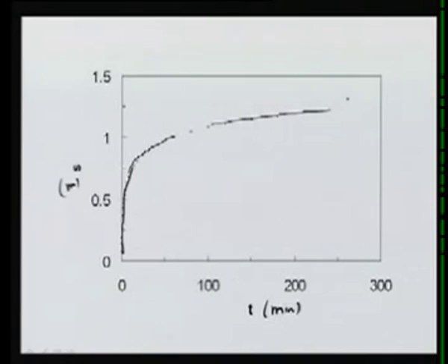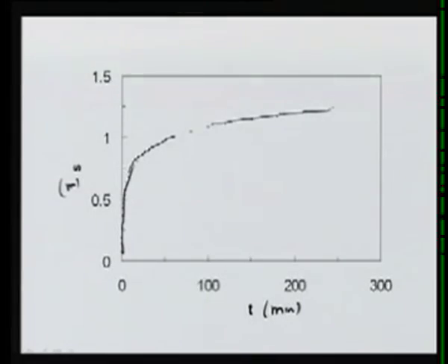It will not reach a steady state because the Theis equation assumes that the aquifer is infinite. So slowly the radius of influence will increase, and there is no limit to it, the increase of the radius of influence. Therefore, this will not achieve a steady state, it will continue to increase, but at a very slow rate.